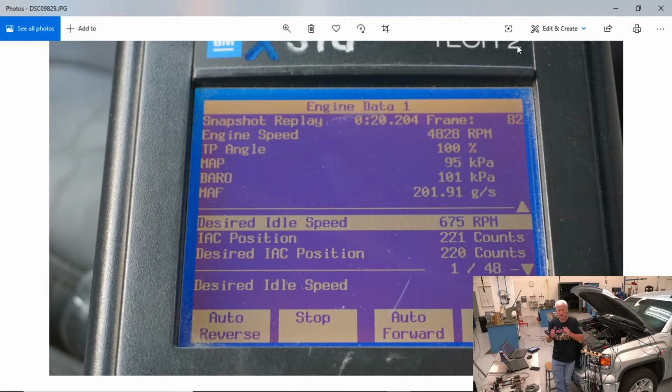If you have an engine spinning at 5,000 RPM, every 2 revolutions should move 350 cubic inches of air. I say 2 revolutions because it's a 4-stroke cycle: it takes 2 revolutions to suck air in, compress it, power, and push it out. That's if an engine was 100% volumetrically efficient.